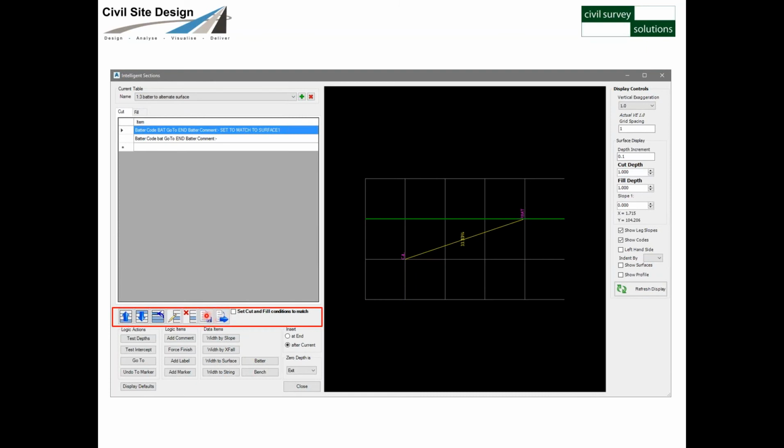Okay, so when you click on save, the save folder will default to your common folder, at which point you can save the template or the section that you're currently working on to your common folder, and every new job that you open going forward, the theory is that it will be in there ready for you to use. You've also got the load option. The load option I'm sure will be useful if you're going to be taking these sections that I'm creating: you can load them in from the zip folder that I've got. Once you've unzipped it and put it in your common folder, you'll be able to paste that and bring these styles in.